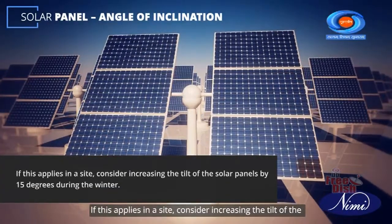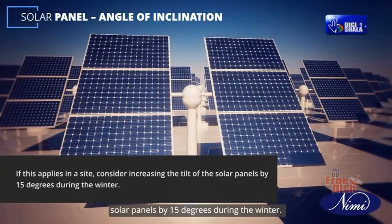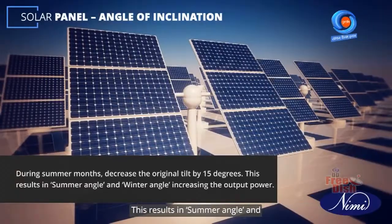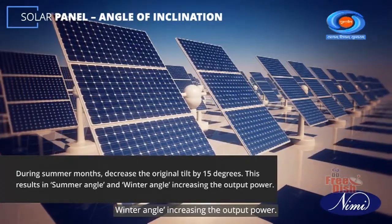If this applies in a site, consider increasing the tilt of the solar panels by 15 degrees during the winter. During summer months, decrease the original tilt by 15 degrees. This results in a summer angle and a winter angle, increasing the output power.